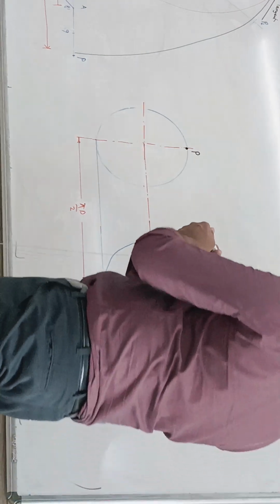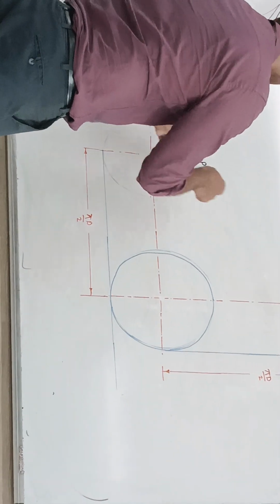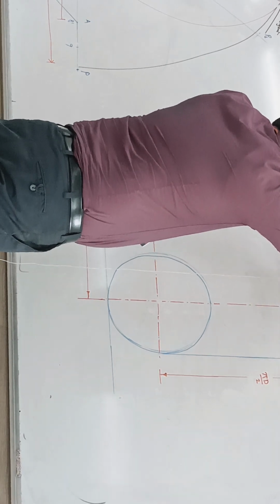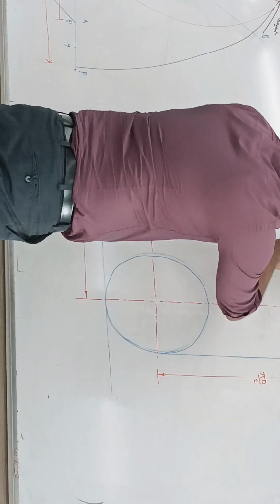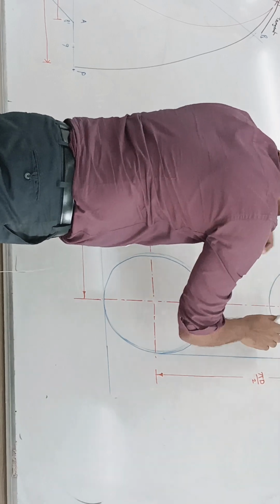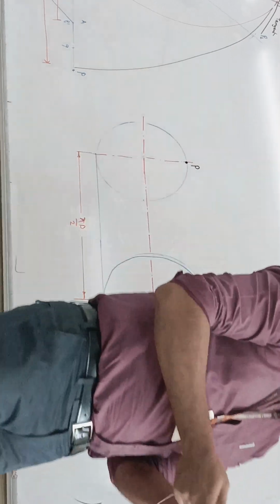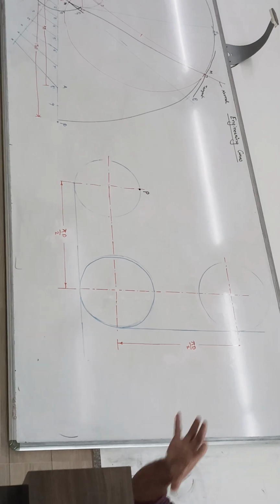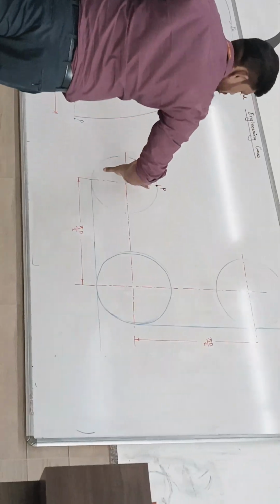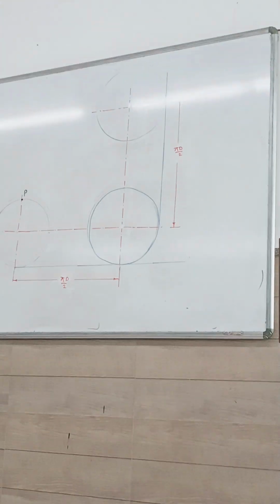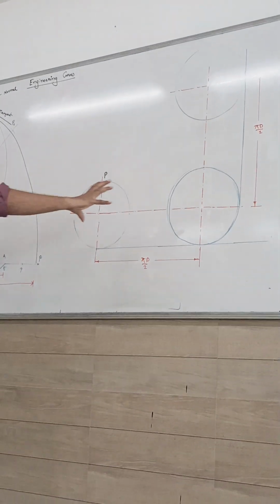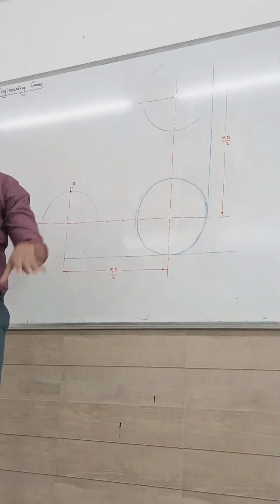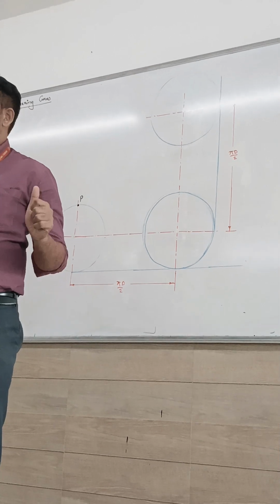Third circle at that point. So take the radius of the base circle. I hope this is clear. We have drawn 3 circles. Now this is the rolling circle which is going to roll for half a revolution on the horizontal surface. It will stop at this position, and after that it will roll on the vertical surface for another half a revolution. Is it clear up to here?